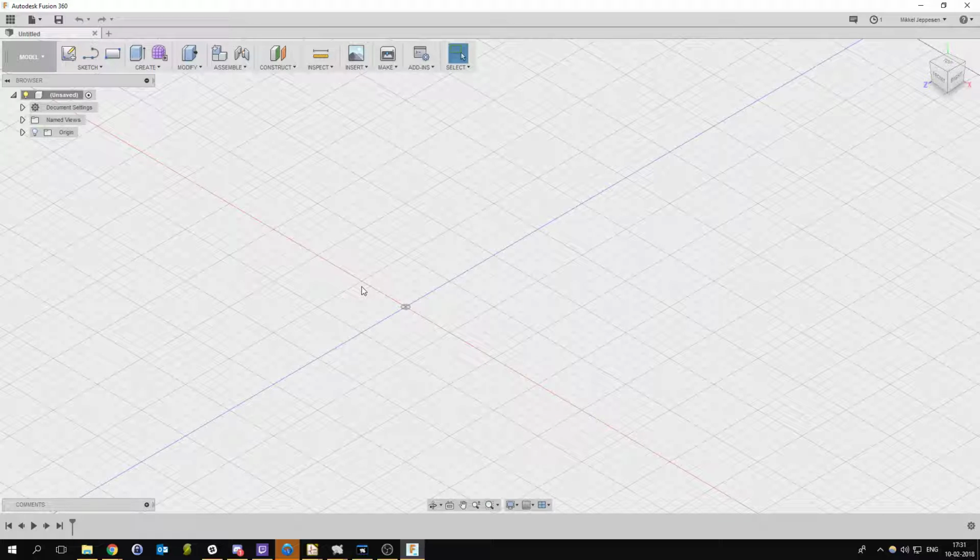is you first make a 2D sketch detailing some sort of form in a two-dimensional way, and then you extrude it in some way. The most common way is just to extrude it straight up. If you want to make a cone, for example, you make two different sketches at two different planes. One being a small circle and one being a larger circle, and then you can call what is called loft between those two, and it'll kind of make a cone.